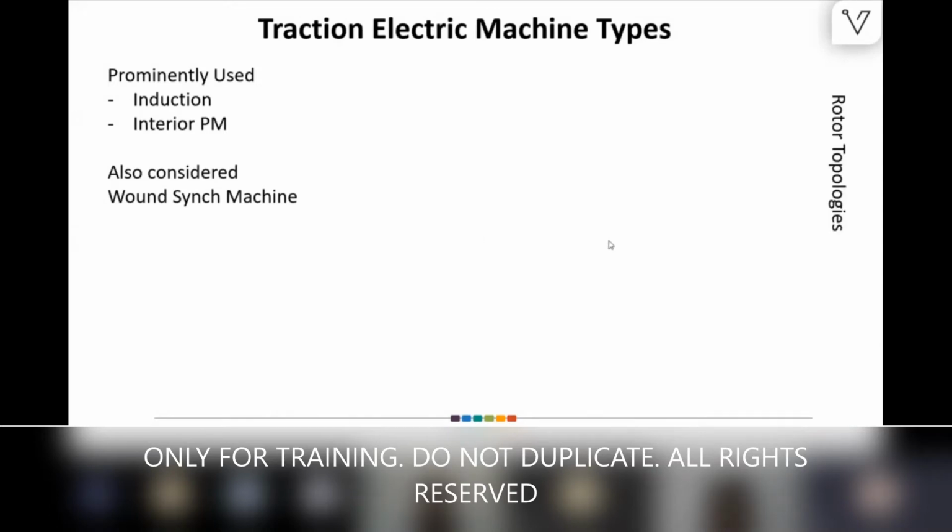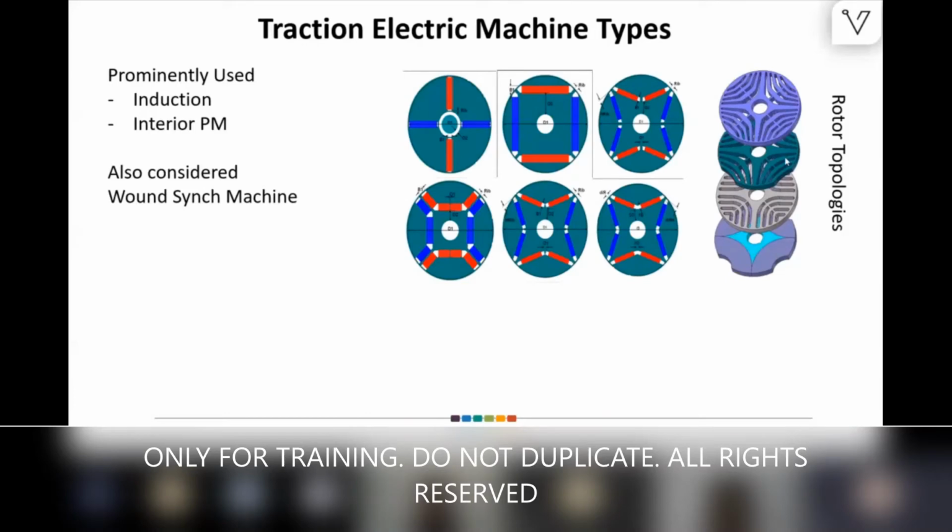As for rotor topologies, you can see topologies like SRM, and IPM, which we call interior permanent magnet. The way we play with the arrangement of these magnets, we get more and more torque density and power density. These are very critical designs. Rotor designs are very critical from the machine perspective, because the rotor also limits your maximum speed.